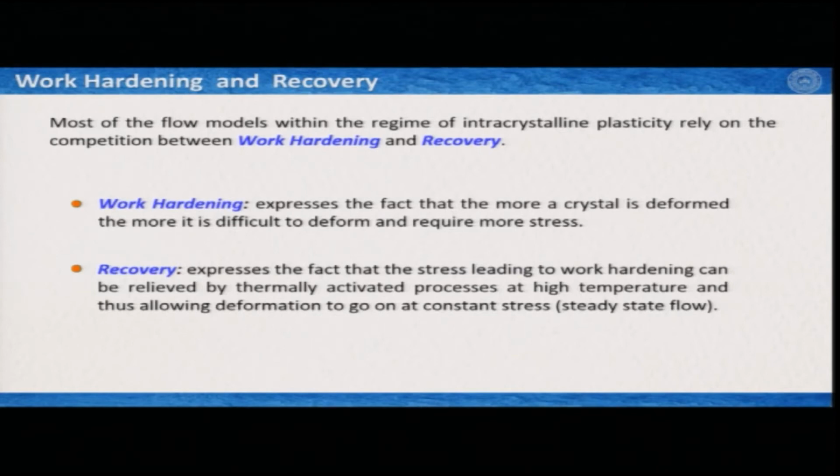So, if I start deforming it, then it requires more and more stress to continue the deformation. If I look at it in the form of a stress strain curve, after the yield it does not flow this way, you need more and more stress to deform it, and this phenomenon we learned is known as hardening or strain hardening.